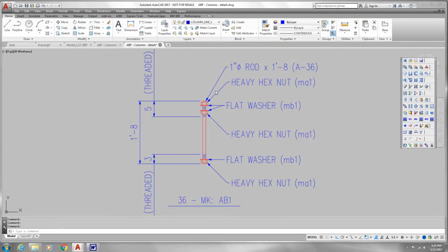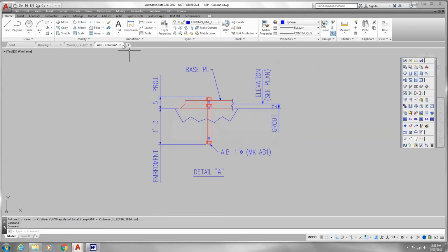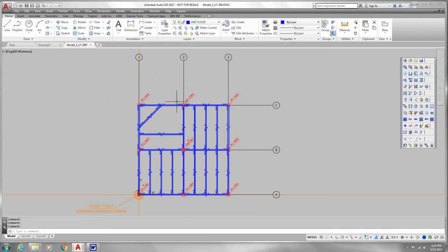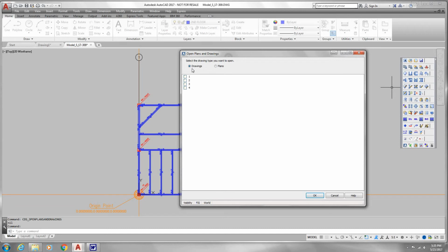All right, we're just going to close up that anchor bolt plan. And we go to this little icon, gives us our drawings and plans. So our anchor bolt plan is over here under plans. We can also make floor plans and elevations to use as e-sheets. And we'll just open up a couple of these guys.